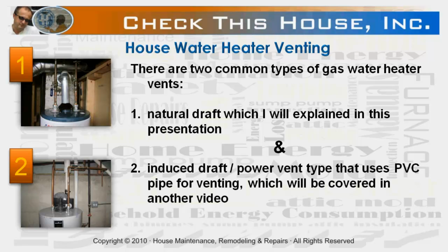There are two common types of gas water heater vents. The first one is a natural draft, which I will explain in this presentation, and the second one is an induced draft power vent type that uses PVC pipe for venting. This one will be covered in another video.